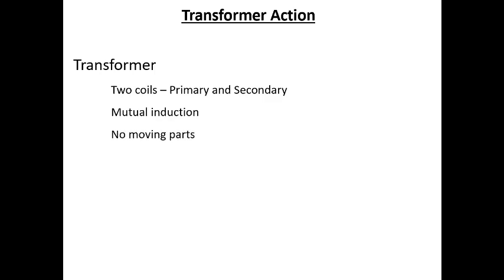Transformers do not have moving parts, so there's nothing to wear out. They last for a very long time. They're very efficient. We can get transformers that are maybe 96 to 98% efficient, which is pretty good. And they're very low maintenance. Many of you who are working in maintenance probably rarely go and fix a transformer. Usually the only thing that could happen to a transformer is it could blow up or it could fail.